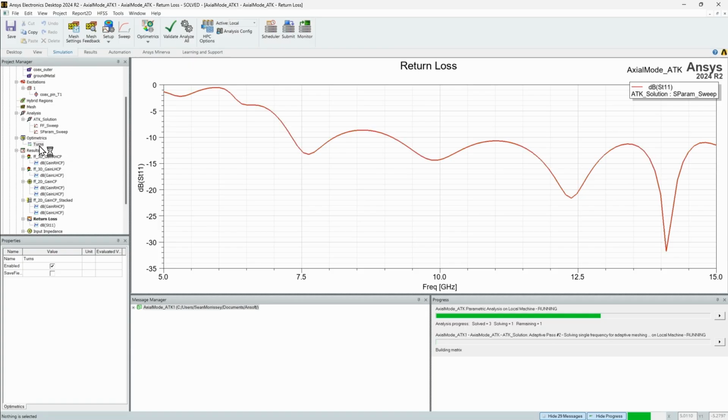So this is a pretty simple sweep. Nothing too crazy. However, you can have multiple different values. So say if we did number of turns and we changed the diameter for each individual value, say we had 3 different values inserted for the diameter. We did 1 centimeter, 2 centimeters, 3 centimeters. For 1 centimeter, it would go through each individual variation of the number of turns, and then the same for the next. So in total, there would be 15 sweeps there. So it can get pretty convoluted pretty quickly.